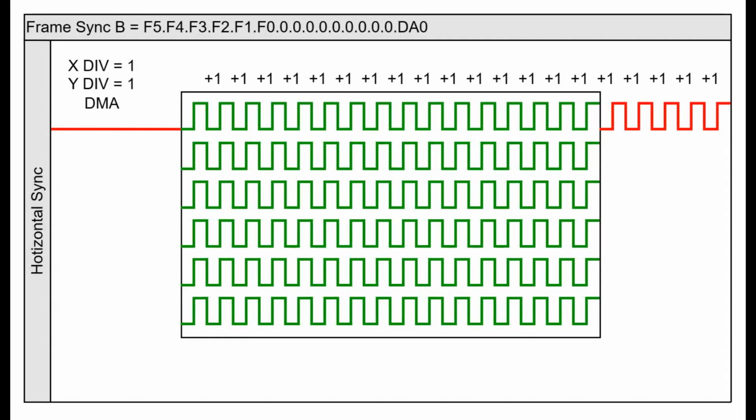This typically means that mode 6 and 7 behave identically on paper, but the VDG has a little trick up its sleeve. DA0 continues to count past the right-hand edge of the viewport. In mode 6, this is hidden as the relevant affected bits are cleared. In mode 7 though, this means the extra bytes are hidden. This would be really useful for horizontal scrolling if the base address could be controlled on a per byte resolution, but sadly this is not the case. It still has its uses, but not what you might hope for.